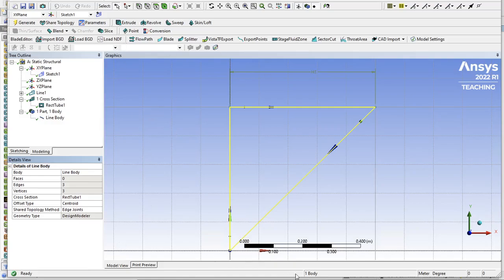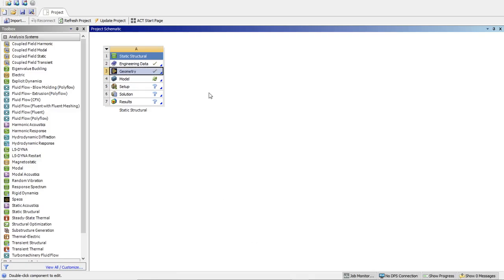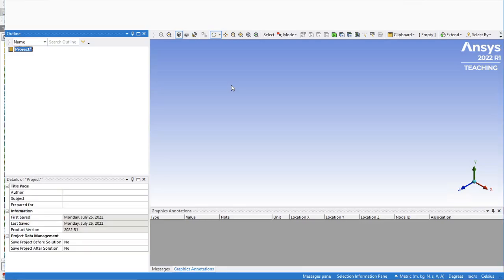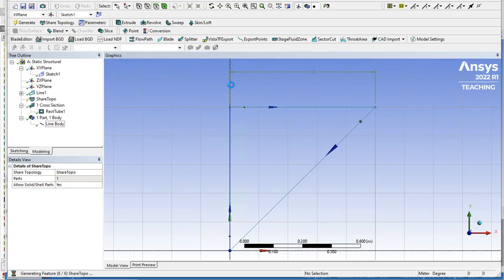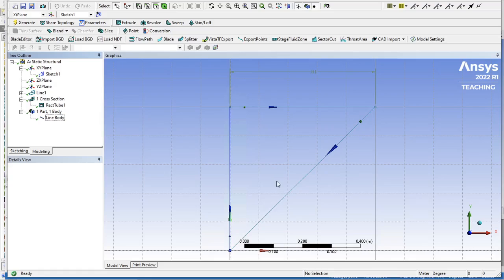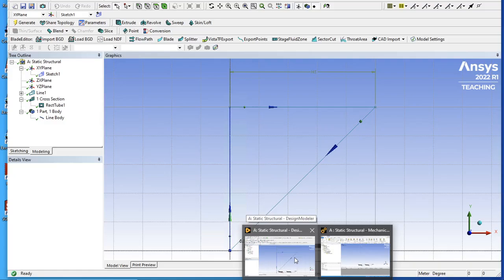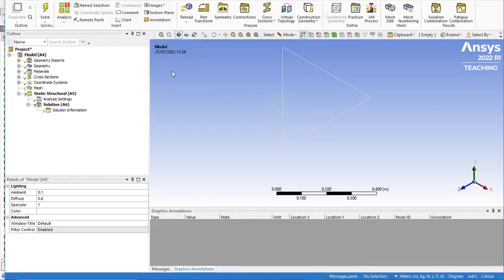Okay, this is done. So we can now go back to the Workbench, and now we need to open the model. So what happens is that now the model will load the geometry, and we can do the rest, like assigning the material properties to that sketch, then meshing the sketch. So we create the actual elements, the truss elements, and then we apply boundary conditions. So the boundary conditions here will populate the vector of nodal displacements, the known elements, and then we apply force or forces, which define the vector of nodal forces.